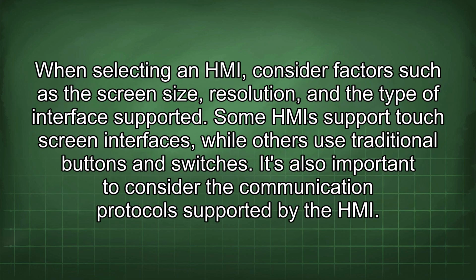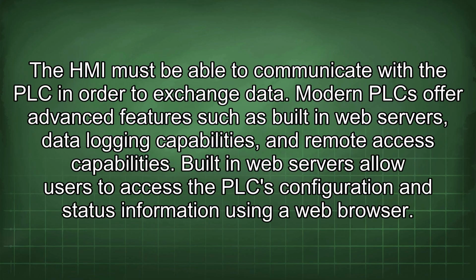When selecting an HMI, consider factors such as the screen size, resolution, and the type of interface supported. Some HMIs support touchscreen interfaces, while others use traditional buttons and switches. It's also important to consider the communication protocols supported by the HMI. The HMI must be able to communicate with the PLC in order to exchange data.